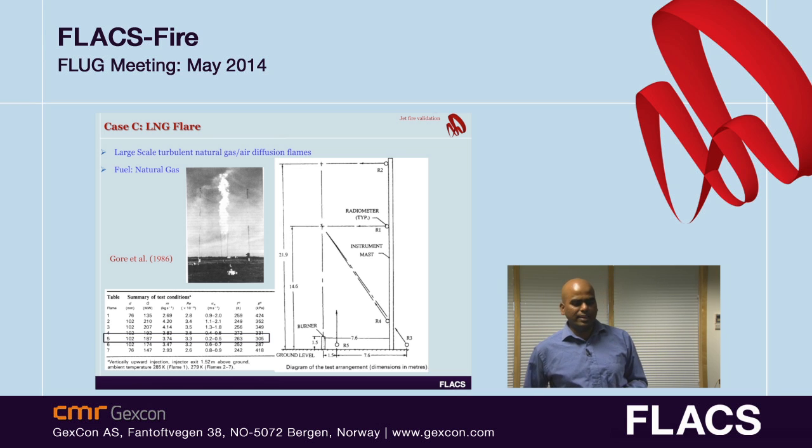My next case is the LNG flare, where I have compared the FLACS-Fire simulations against the experimental measurements. It's a large-scale turbulent natural gas diffusion flame, where the fuel used is natural gas. This table shows the summary of the different cases. So I have chosen case number 5 to present here.